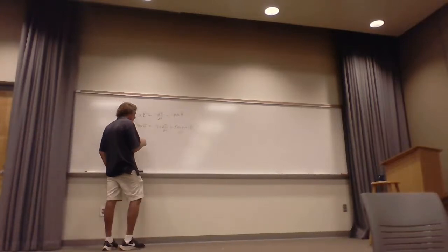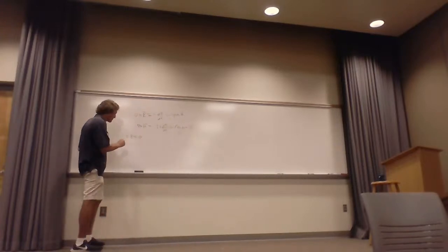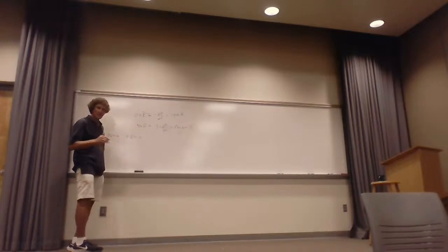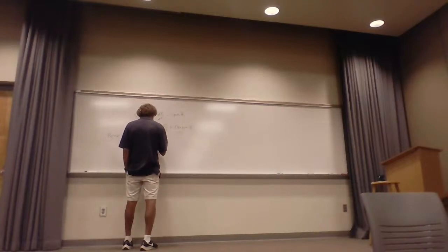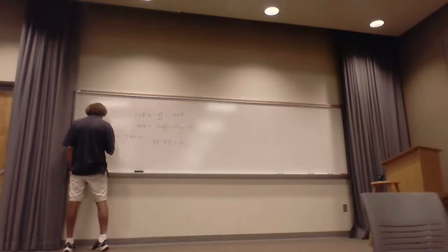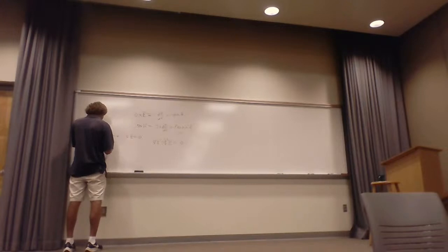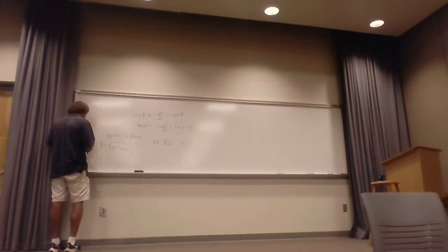We got one equation with one unknown, and we set the divergence of E equal to 0, because rho V was 0, right? And then after that, we got one equation with one unknown. It was this crazy thing. We had del squared of E minus gamma squared E equals 0, and gamma, I don't have time to go through all of it. Gamma was equal to the square root of j omega mu times (sigma plus j omega epsilon), and gamma was equal to alpha plus j beta.